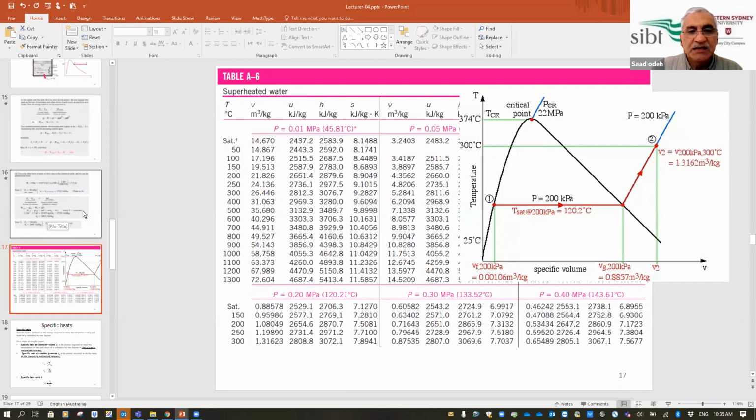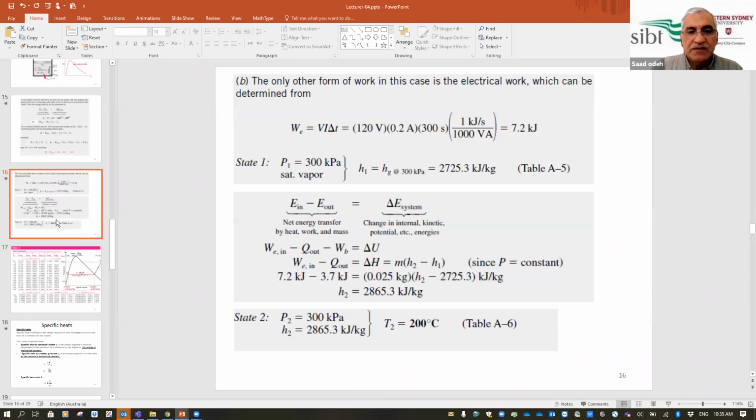So if we want to find the energy balance of any system, we have to add all the values of the work input or exit from the system, and all the heat input and exit from the system, plus the change in internal energy, kinetic energy, and potential energy. Remember these system energy terms.